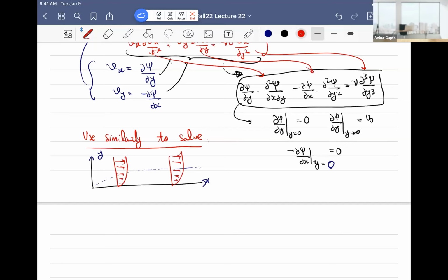We thought concentration difference was self-similar. What do you think should be self-similar in this problem? The boundary layer, right? The velocity profile is increasing in boundary thickness, but what if I normalize by the boundary thickness? Would that yield a self-similar solution?